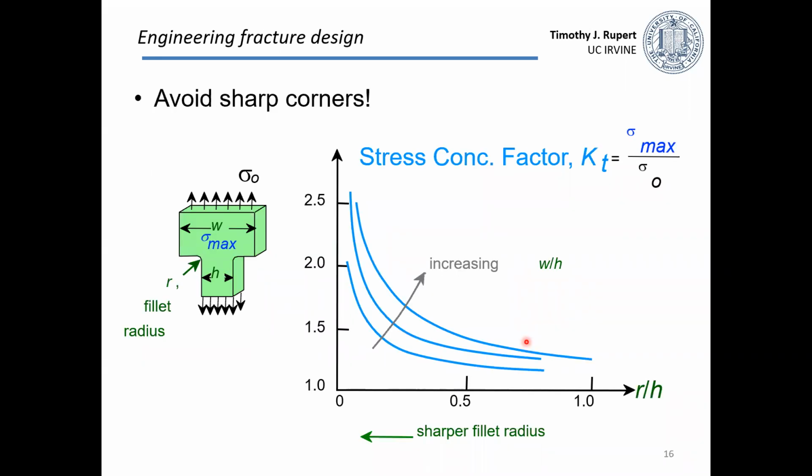Okay. So just from an engineering perspective, that tells us something important. That tells us that we don't want many cracks. We want them to be pretty blunt. But also, if we're designing something, we're making some part, we're putting in stress concentrations there too. And if we did this, we would want to also avoid sharp corners.